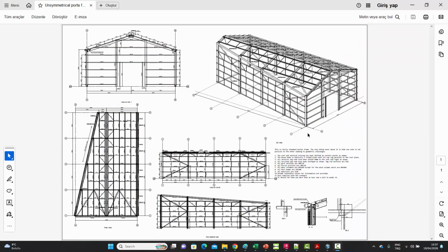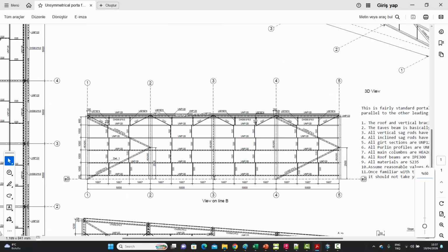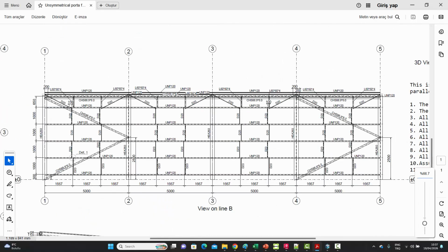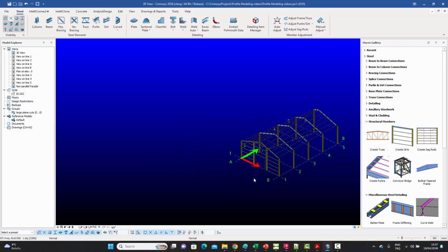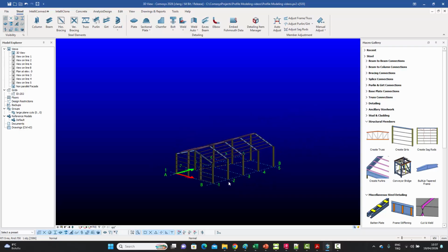Now, coming back to the drawing, we want to do the backside, the girts on the backside as well, and the drawing is over here. We can see that the girts are pretty simple, following the same pattern of 300 and then 1000. So we go back to the model. We can easily enter it directly over here as well if you want to.